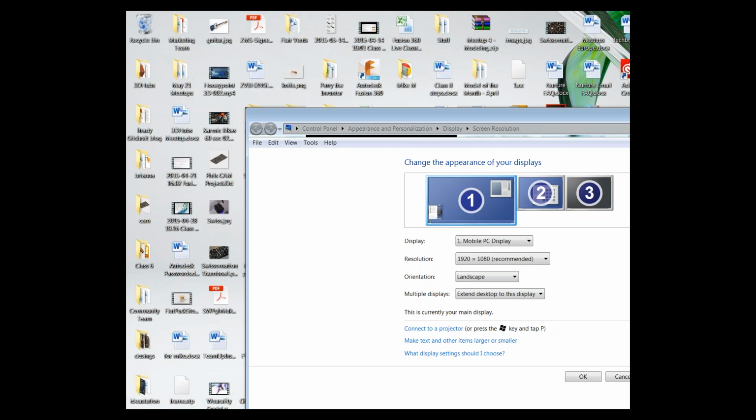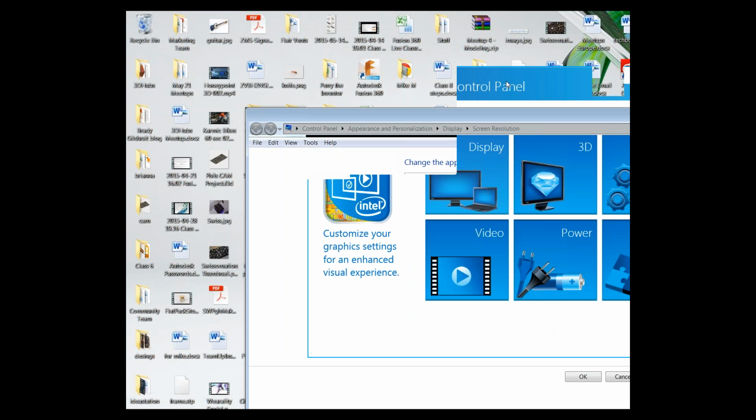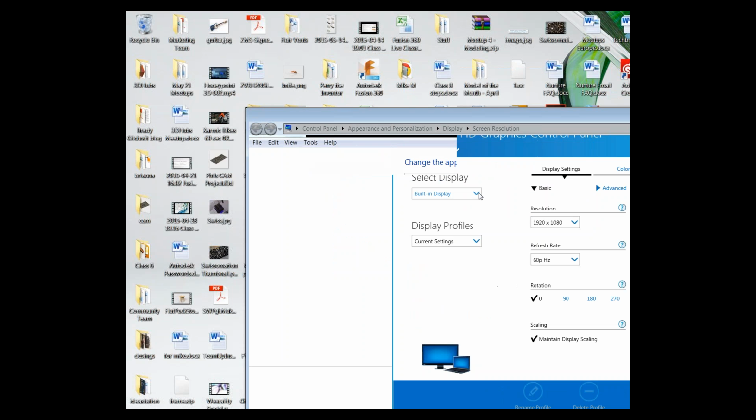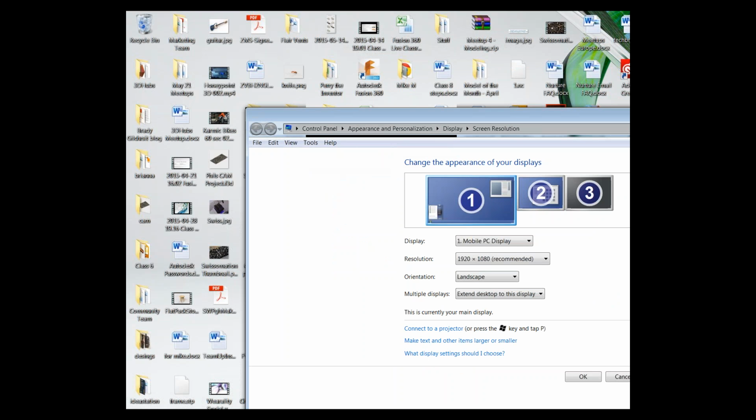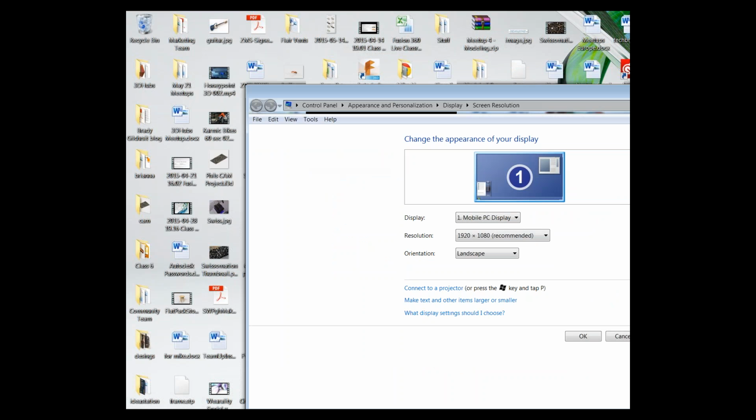Okay, so I have not taken the SBU on the Tormach. So is that something where the milling tool rotates around? No, the milling tool in this case is fixed, moving in X and Y on the bed with Z changes on the spindle. If you do need to use fourth axis, let's say you're milling a gear, you can add a fourth axis to the machine, but to do that code, you would have to use Inventor at the moment, or you would have to use VCAR.